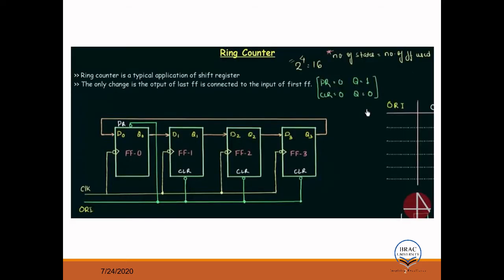Let me use the laser pointer. Okay, so we'll discuss the ring counter. Ring counter is a typical application of shift register. The only change is the output of the last flip-flop is connected to the input of the first flip-flop. So if you look here, the output of the last flip-flop is connected to the input of the first flip-flop.